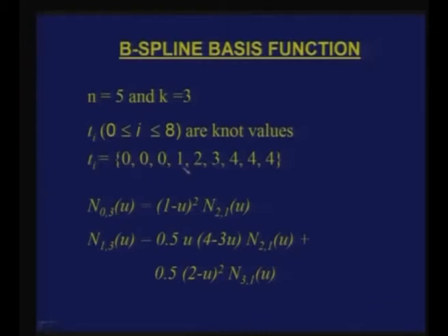If you see here, these are zeros at the ends, because k is equal to 3, and these are 3 values, and the other 3 endpoints are all 4s, and in between it is increasing in ascending order. So, the knot vector automatically comes up in an order which is required for a non-uniform B-spline curve definition.